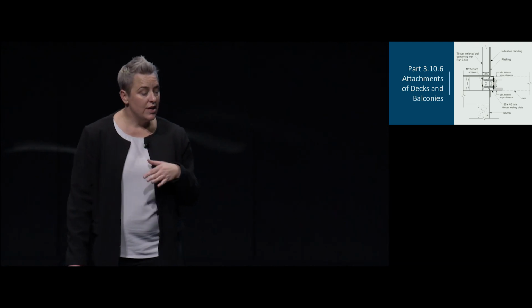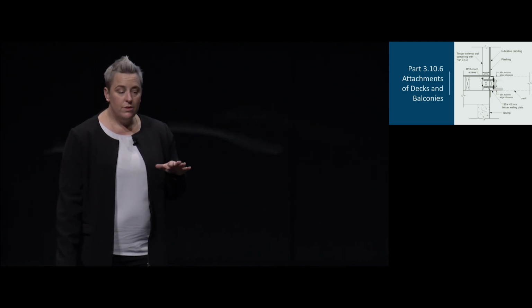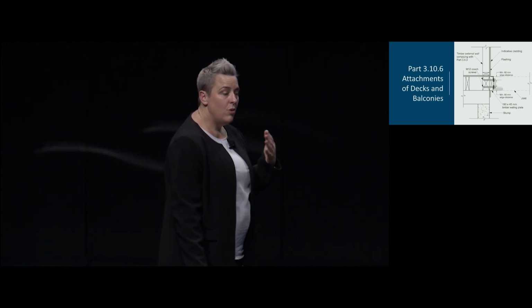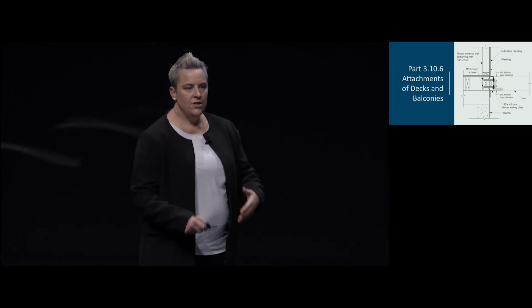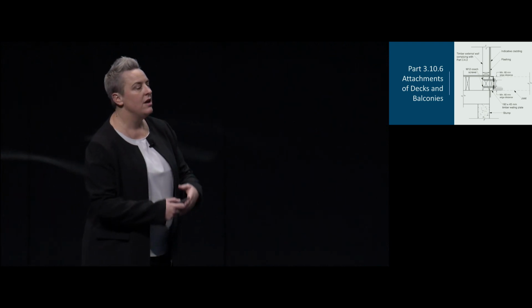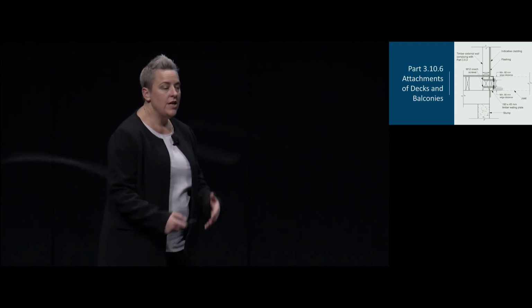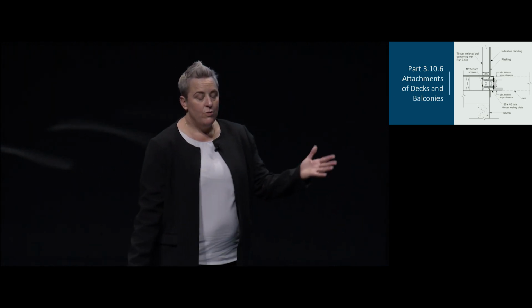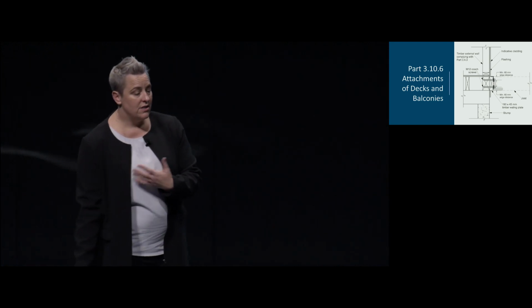There are other limitations in using the acceptable construction practice, which include that the height is not more than 3 metres, with imposed load restrictions of 2 kPa, which is your typical normal domestic activities. So it's an important consideration when designing to determine whether or not the owner is intending on putting gym equipment, an outdoor kitchen, a spa and so forth. If they're loading up the deck, then they may actually exceed the 2 kPa, and then it would be out of the scope of the acceptable construction practice and you wouldn't be able to use it.